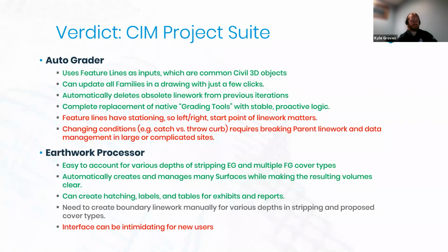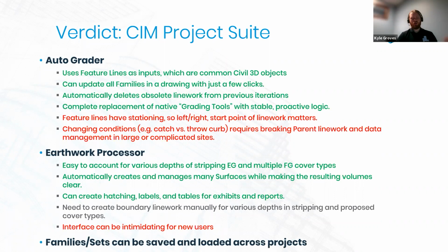The con for Earthwork Processor is if you don't know a lot about how Civil 3D wants you to compute these volumes, the interface can be a little confusing, and it's tough to follow that thread all the way through. But like I said, check out my webinar from April of 2021, where my coworker Brian Tanner and I, from the same time, go all through this tool and out-of-the-box workflows in detail. The other thing with both of these tools and many others inside the CIM Project Suite: these families, these sets, these criteria can be saved out to a central repository and loaded back in for different projects.